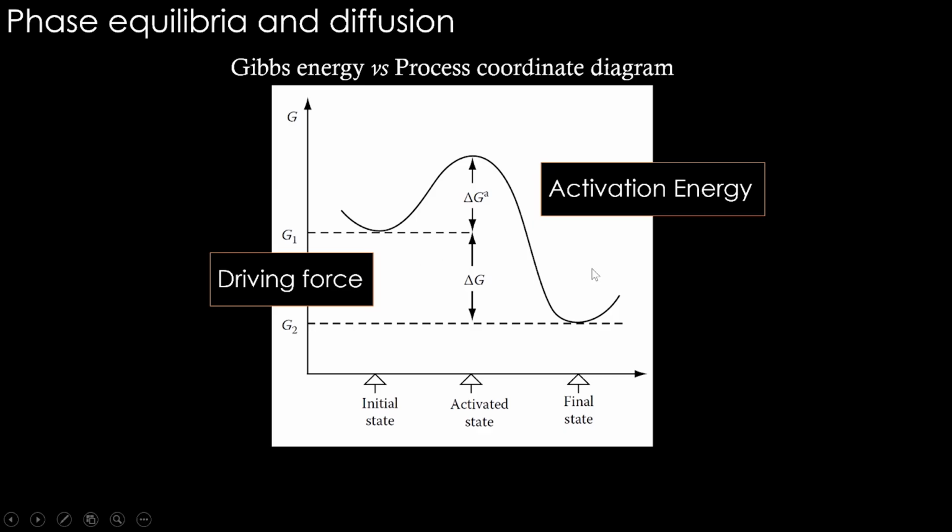So keep this in mind. Okay. Now, the important idea is this. Let's say in the initial state there are areas of high concentration and low concentration. The final state is when everything becomes uniform. What I'm trying to say is, the concentration profile scenario that we saw, high concentration to low concentration, if that becomes uniform, then the entire material goes to lower Gibbs energy, let's say. In that case, the process is actually driven because we are talking about a lower Gibbs energy state as the final state. Gibbs energy also favors this high concentration to low concentration becoming uniform. Okay, this is not random jumping alone. There is a Gibbs energy driving there. Because the opposite also is true.